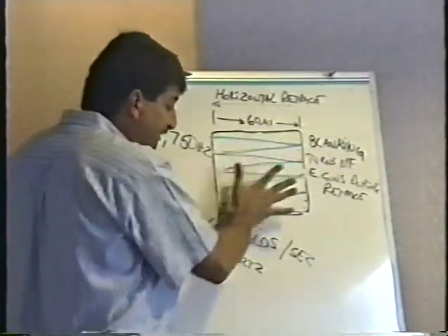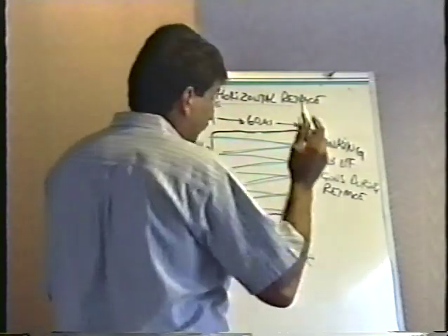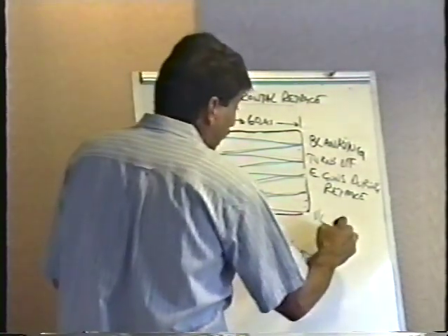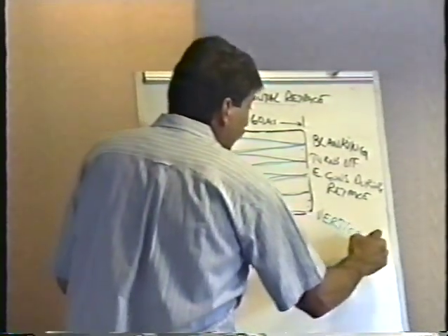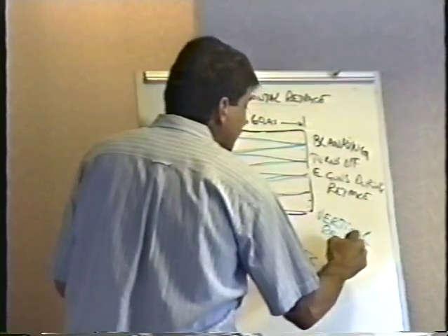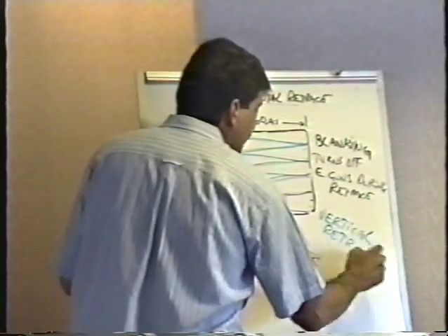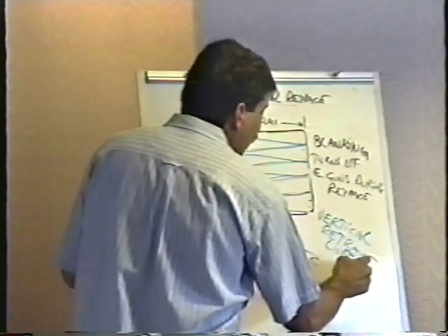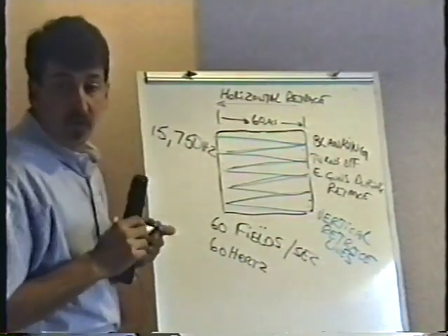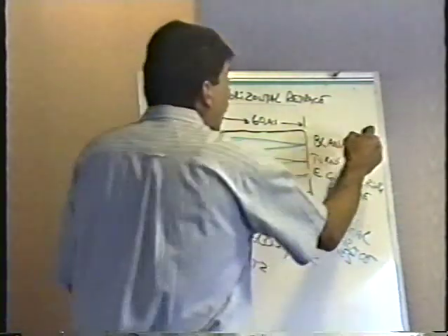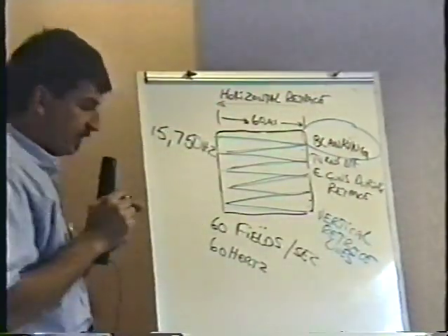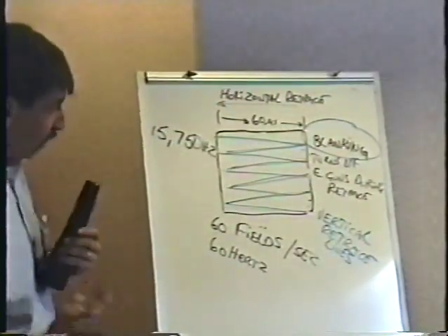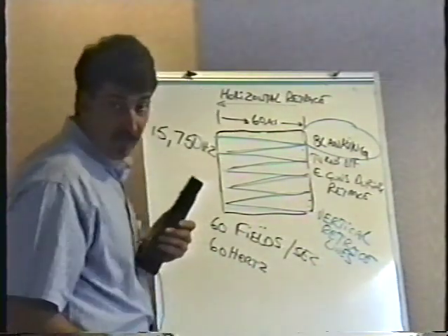Now, you don't see these lines. These lines, I'll demonstrate them to you in just a second, are called vertical retrace lines. There's a very important reason that I point these out to you. Normally, you don't see these vertical retrace lines because of the blanking circuit. The blanking circuit turns off the electron guns during the retrace time.